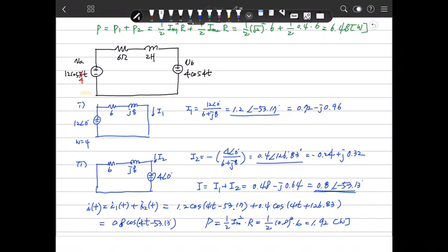So it's perfectly different. I mean, this is 6.48, but when you have the same frequency, the result is different. So when you calculate the voltage and current, you can use the superposition as you want. But when you calculate the power, you can use the superposition only when the frequencies are totally different. If there are same frequency sources, then you cannot use the superposition, because when your frequency is the same, the power is non-linear. The superposition is a property to be applied to linear systems.